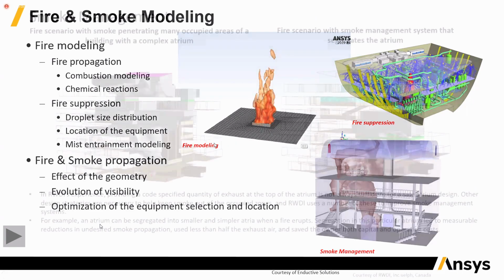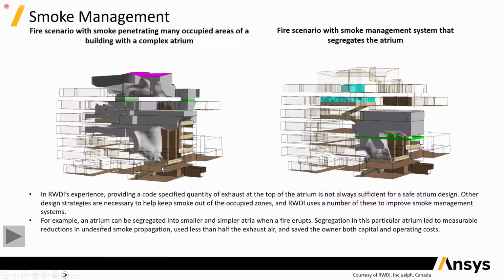You want to understand how smoke behaves inside your building, how smoke disperses from the ground level towards the upper levels of my building. How do you ensure that your smoke exhaust ventilators will properly exhaust the smoke that is generated in the event of a fire outage? Do you need to burn the building to know that your design is correct? Normally, no. You just use a CFD analysis.